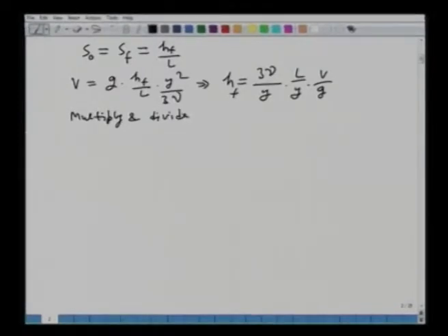Okay. I can multiply by a constant, or one quantity in both numerator and denominator of an equation, right. So, what I do is I multiply and divide this equation by 8v. If I did that, you would see that hf would be equal to 24 nu over v times y. This I collect together, then L over 4y. All right. You have multiplied by 8 in the numerator, you are multiplying by 8 in the denominator.